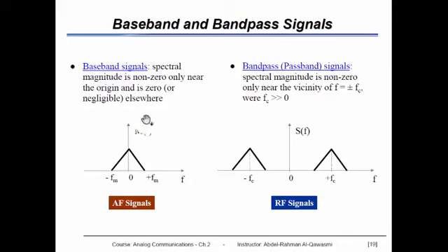If you want to multiply your baseband signal, with low bandwidth and low frequencies, with a sinusoid of high frequency FC, this frequency should be very high to make such a shift in the frequency domain. It is a requirement, as you will see in the future, in order to be able to transmit the band pass signal over the antenna.